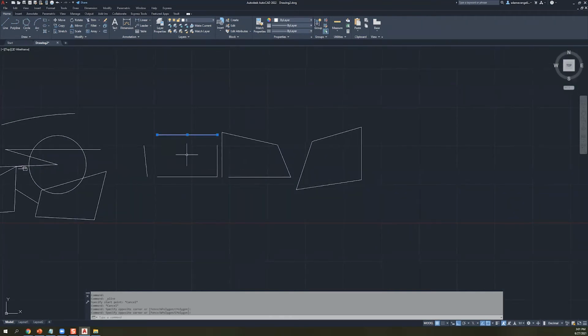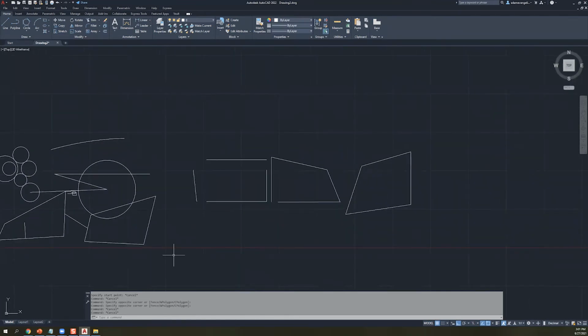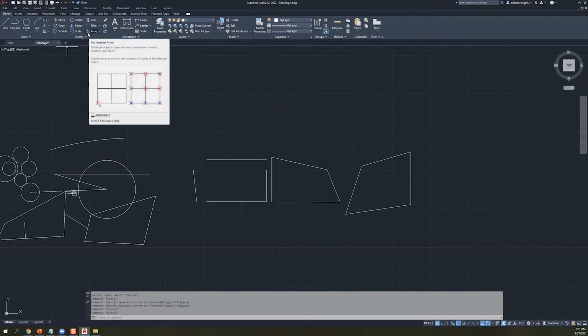Once you're comfortable with drawing and basic geometry, it's good to keep in mind how AutoCAD operates from here. I'm obviously skipping over modified geometry because it's not that important to this discussion, but what happens next is that you populate your drawing with various types of objects. You draw shapes, squares, circles, polylines, what have you. What happens next is that each of these objects is defined by a variety of properties. If you want to see these properties, you just type in properties and then hit enter, just like that.